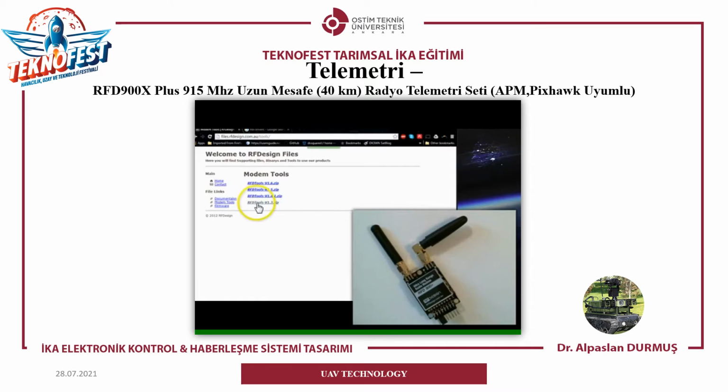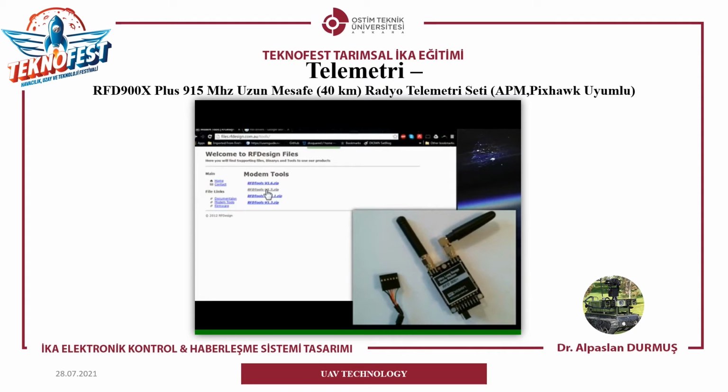We have used versions 1.3 through 1.5 with no problem, and they are sufficient for our needs. 1.6 has been kind of buggy and unstable. Therefore, that's why we're sticking with version 1.5 or earlier. You will also be using the FTDI cable. It's a little 1x6 header on one side, USB-B male connector on the other side. This is the same cable that is used to connect the ground station antenna tracker to the ground station computer.